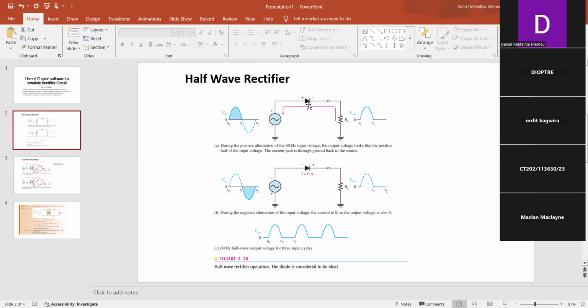in the opposite direction. And so if you take AC voltage and pass it through a diode, as shown in this first diagram, then connect your load, which for this discussion let's assume is a resistor as shown, and back to the source, so that you build a circuit like this, then you have what we call a half-wave rectifier. How does it work? It works this way.